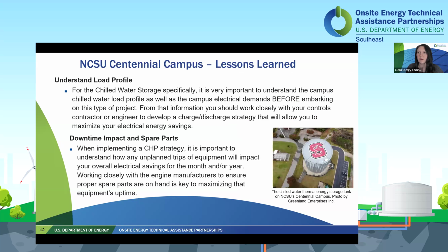Next thing is to understand your load profile. For the chilled water storage specifically, it's important to understand the campus chilled water load profile as well as the electrical demands before you embark on this type of project. And from that information, you can work closely with your controls contractor or engineer to develop a charge and discharge strategy that will allow you to maximize your electrical energy savings.